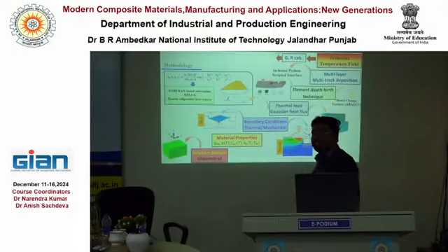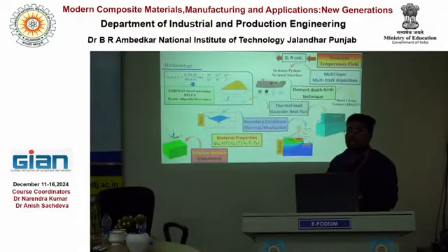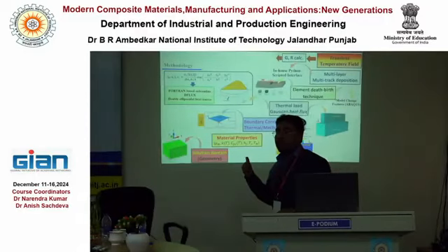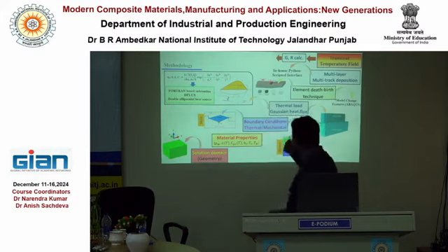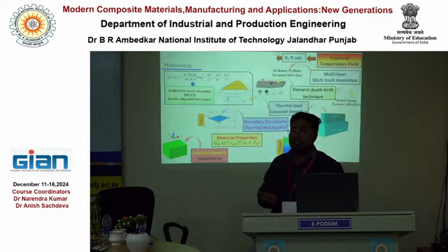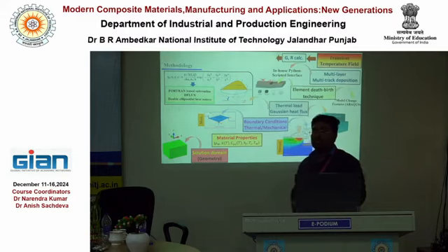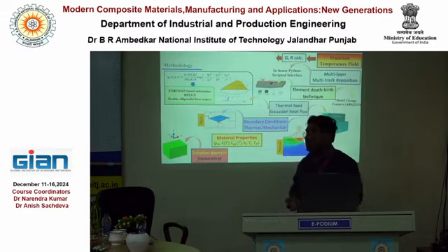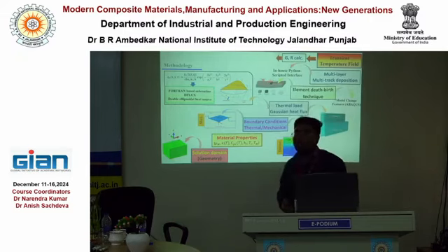Now on the basis of the time-temperature history, what can we actually calculate? The G and R calculation we can do on the basis of the transient temperature output from the thermal analysis. So what are G and R? G is basically the temperature gradient. These are the solidification parameters. Solidification parameters are very important if we are thinking of any product made by a deposition process or any other process. If we deal with any temperature-assisted process, we need to take care of G and R, meaning the solidification parameters.